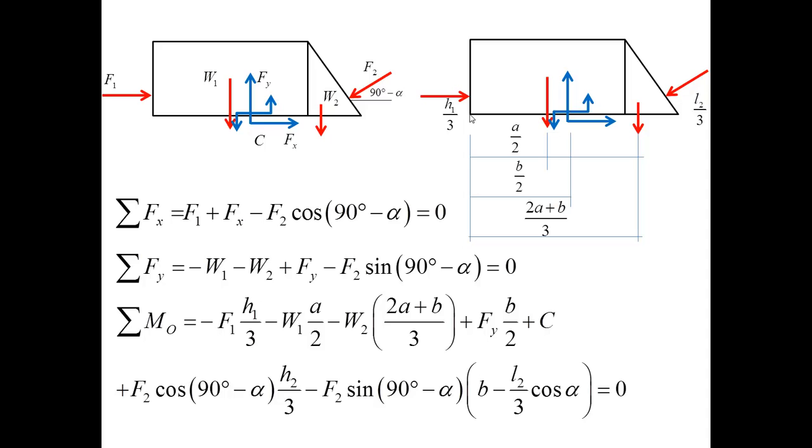This point does not help me with eliminating forces from the equation as we usually do, but I like this point because I'm comfortable calculating arms for various forces involved in this picture, and therefore I choose it, and as a result we have a longer equation maybe than necessary, but every term is easy to identify.